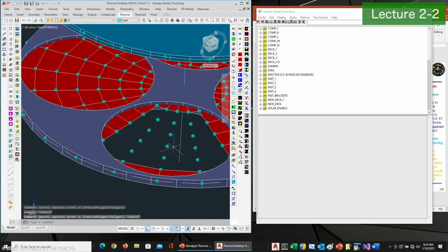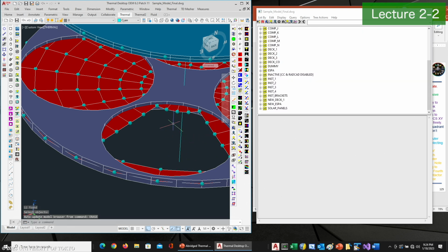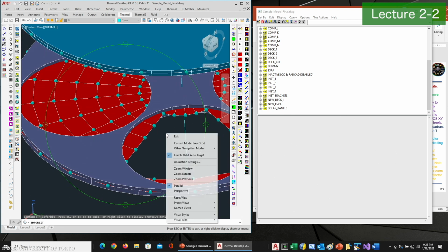And one other trick, when you want to select something, so say I want to erase, you can do a window polygon and a crossing polygon. So if I type in WP, I can now select multiple points. So this lets you more easily do a funky shape for a window to select things. And likewise, you could do a crossing polygon, which would be similar to if it's contained within the whole area or not. Do it.